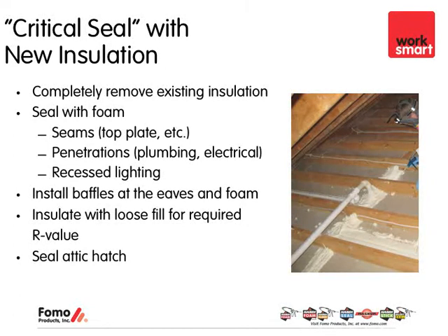And then you want to come back and insulate with insulation again. It could be loose fill insulation, fiberglass, cellulose. It could be batts potentially. What this could allow you to do is that if you want to increase your R value from what you had before, this allows you to be able to do that by putting the right amount of loose fill insulation or fiberglass batts in. Again, still want to also address and seal the attic hatchway.